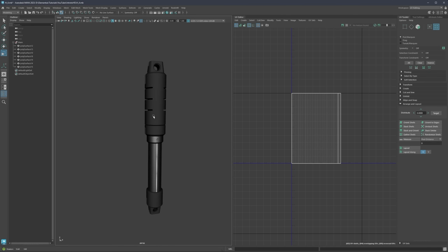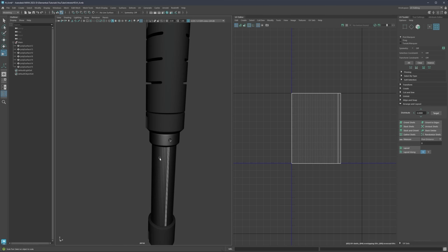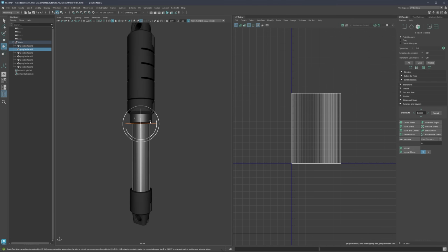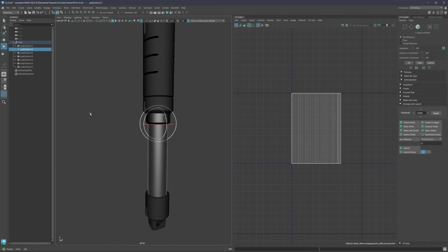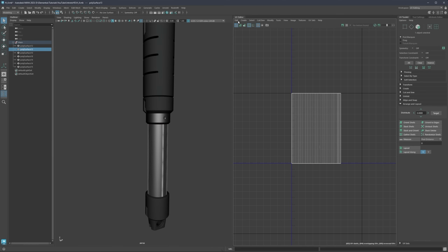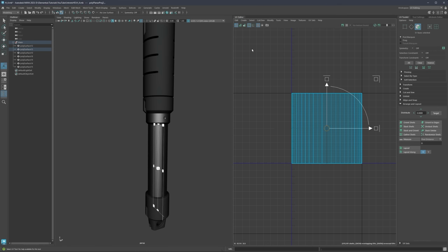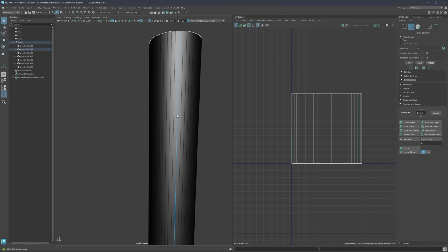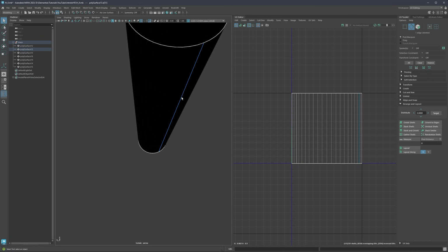Ideally, if this is your frontal view, you want to hide seams all the way on the back. So what you see here should ideally be hidden on the back. These hard white lines, ideally you want to hide on the back. If you notice that that is the problem, what you can do is redo all of this. So let's go to Create, and again, New Planar. Now you're going to have a clean slate, which means we can come here on the back and create a new seam here on the back.